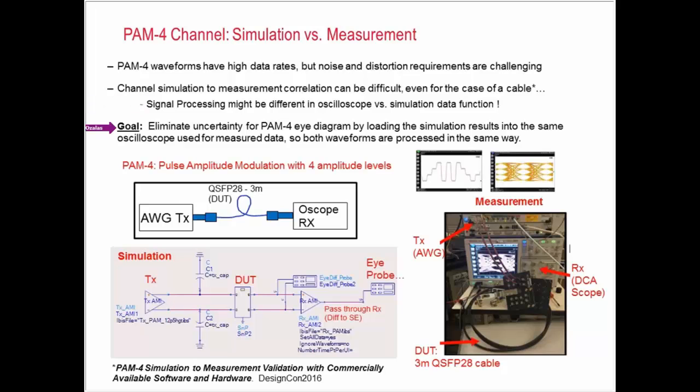So the goal for this exercise is really to eliminate that uncertainty for this PAM-4 eye diagram by loading the simulation result into the same oscilloscope that we use to do the measurement. That way both waveforms are processed in the same manner.